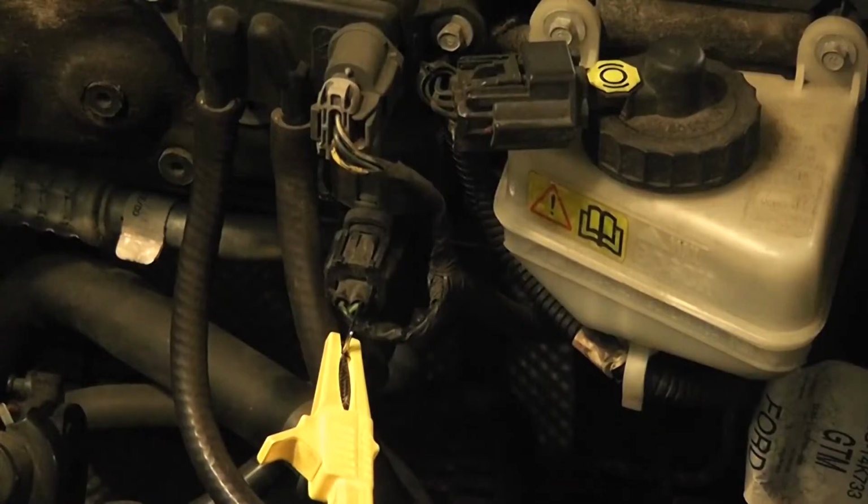All right, so with this EVR trouble code, we're going to start with testing the EVR solenoid for voltage on both wires. This being a ground side switch circuit that with the key on is not being energized, we should have two 12-volt feeds, one going in, one coming out on this solenoid. So we'll take our first of our two measurements, the wire to the right.